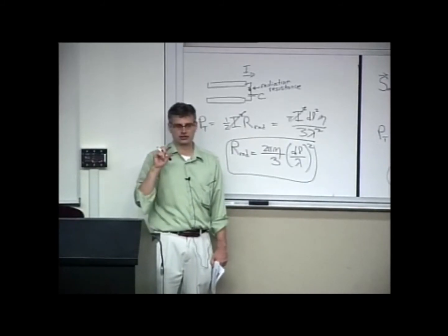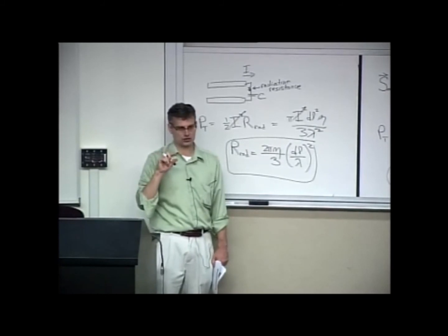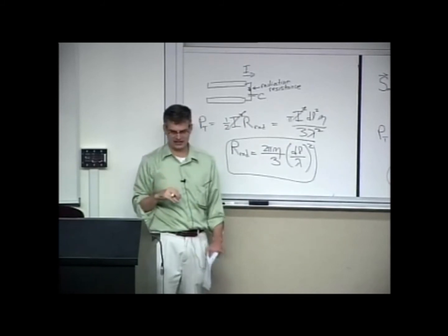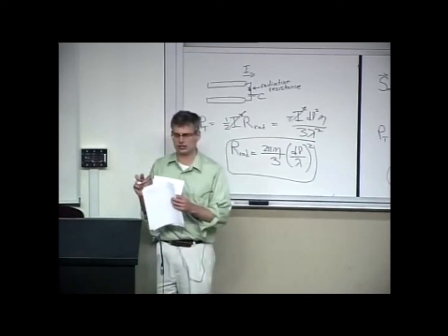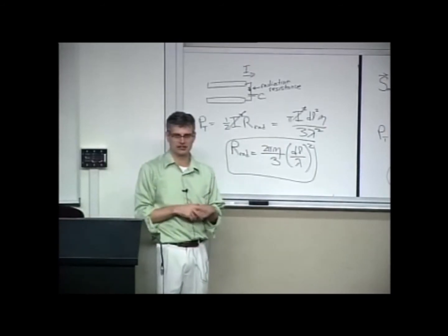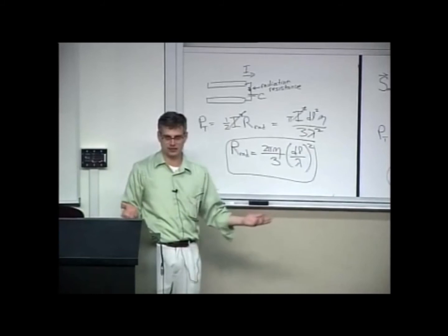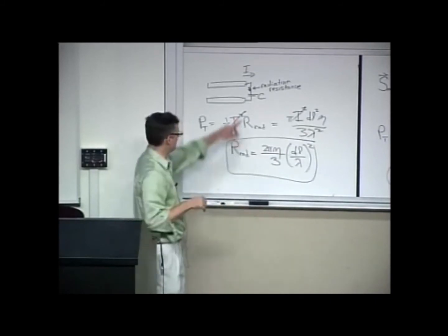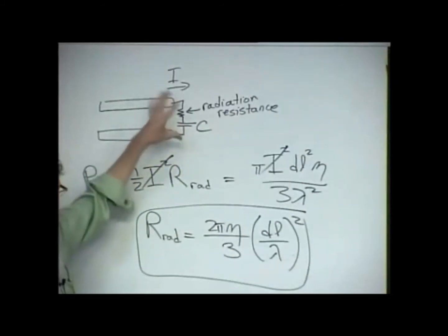When I have electrically small radiating structures that are lines of current, they wind up being very capacitive. And this is why you don't use tiny, tiny antennas with respect to wavelength, not if you want to actually receive something. You have to give it some electromagnetic length, and that makes the C go away and the radiation resistance go up.